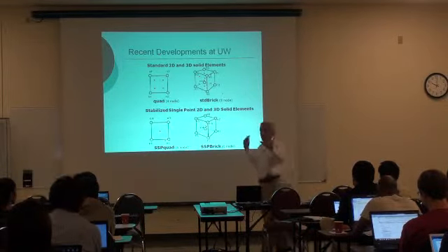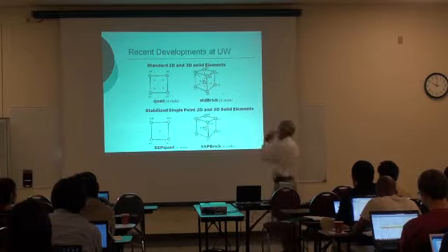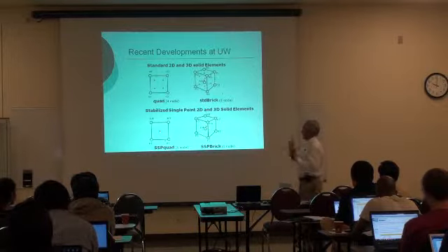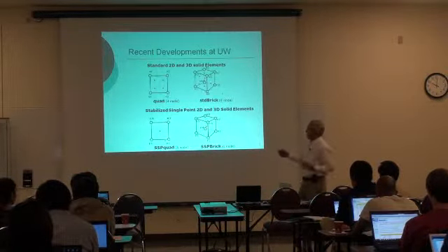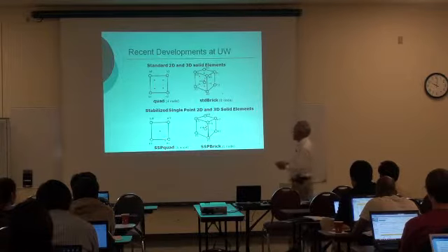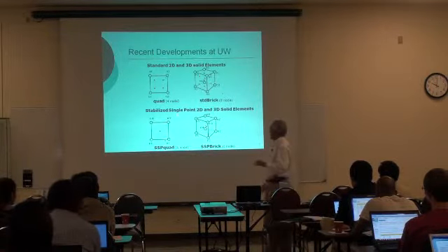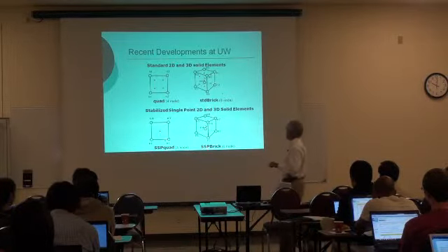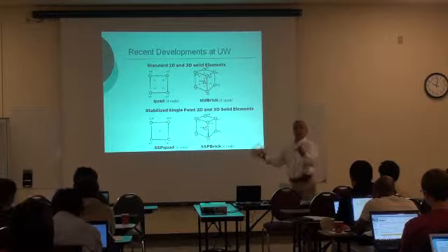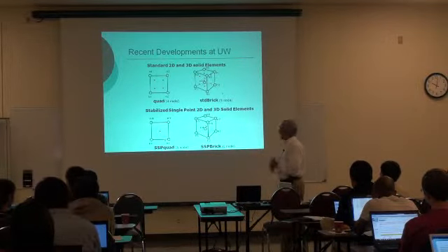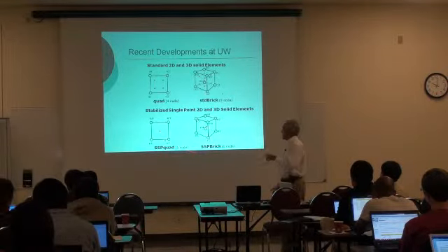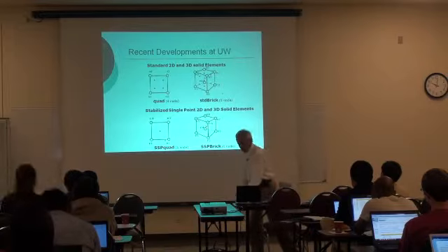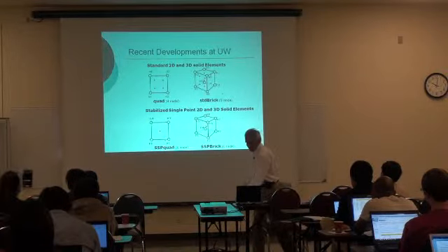Of course, doing this is not something simple because you have to stabilize this element. There are spurious modes, hourglass modes, that you have to eliminate. I will mention a little bit more about this later in the second presentation. But I just want to mention that we have implemented this stabilized single point quad and stabilized single point brick elements in OpenSees. It's available in the code. And we are testing them. We have obtained very good results so far. In the 3D one, we are still doing some work because I am not completely certain that we are getting what we want there.